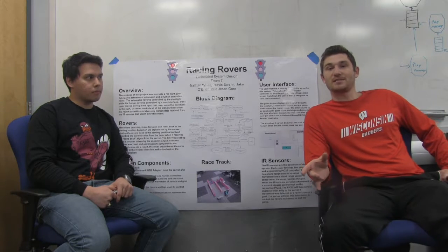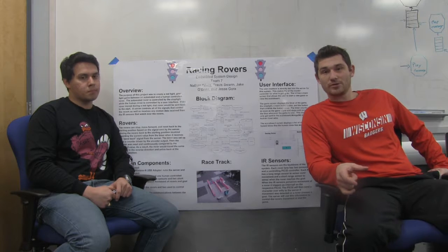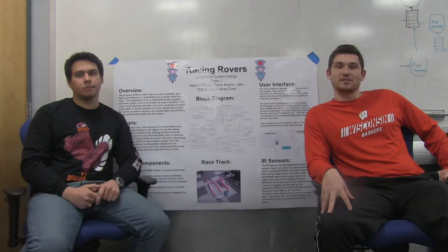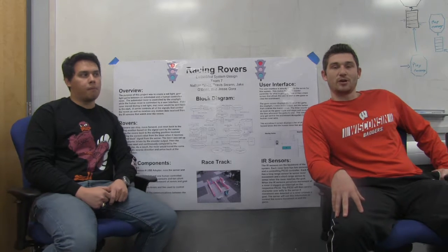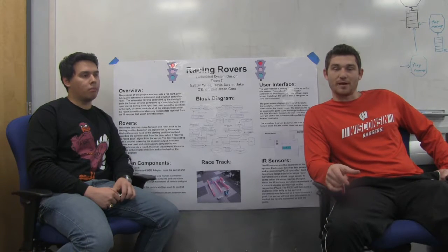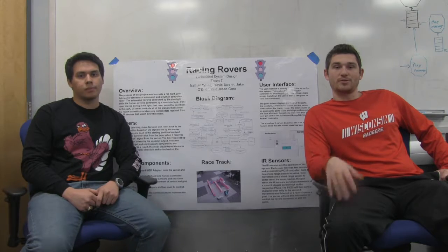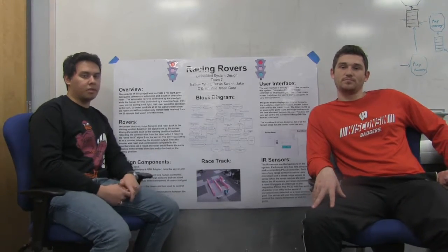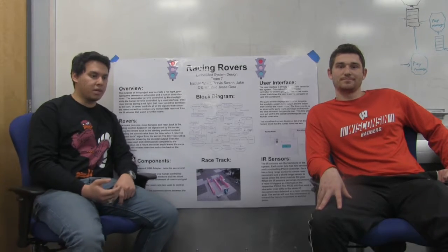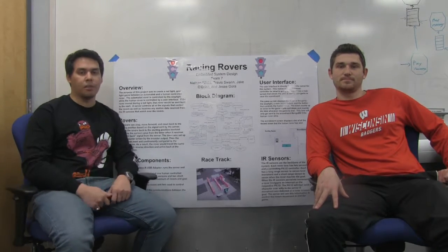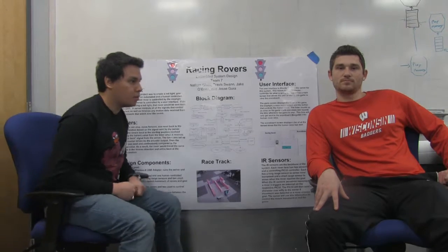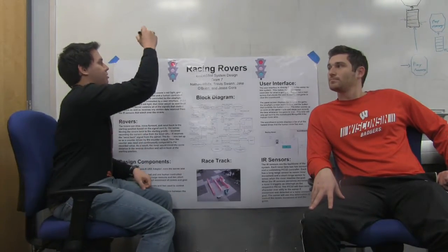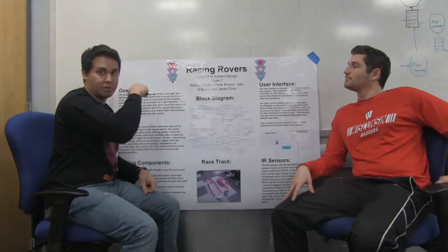The next step was hooking up the motor encoders to the PIC32s as well. So I went through and looked at the data sheets and figured out which pins we had to hook up to the motor shield that were provided to the actual motor encoders. Afterwards, after both motors were hooked up to the PIC32, the next step was getting the motors to run and driving them using pulse width modulation, which drives off the duty cycle of a wave that is being produced.